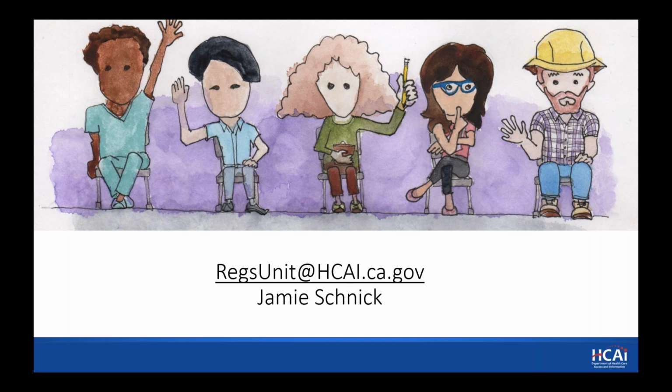The intent is that the new work follows the code. The code requires short circuit ratings. Obviously, if you're doing anything that's going to affect the short circuit rating, if you're adding motors, adding transformers, or, like we talked about, supplementing the normal power service with distributed energy resources, you would need to go do the calc and label it.